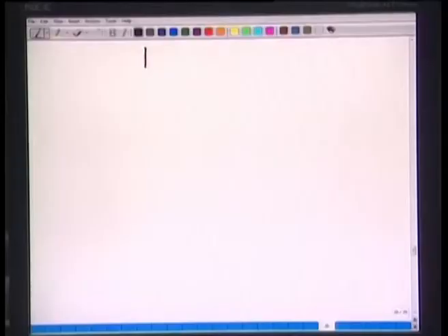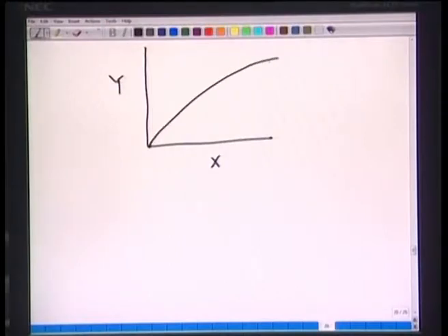So let's redraw our equilibrium curve. We had x and we had y. We have this equilibrium curve, y versus x. Let's draw cocurrent. So we start with P, end with Q, with the slope of minus Rs over Es. All right. So the leaving streams compositions here is y1, and let's mark this as x1, and the leaving stream here, the composition is x2.